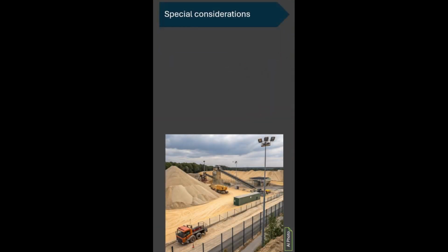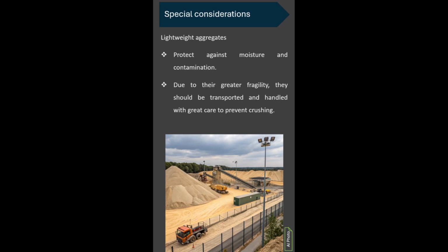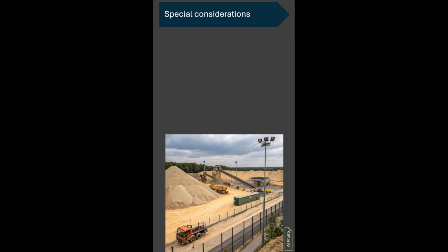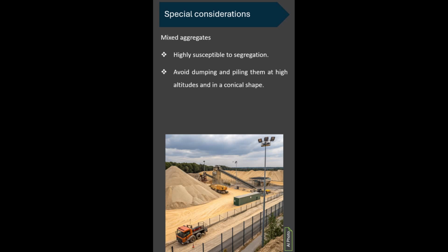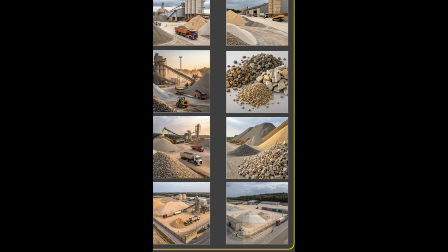Special considerations. Light aggregates protect against moisture and contamination. Due to their greater fragility, they should be transported and handled with great care to prevent crushing. Mixed aggregates, highly susceptible to segregation. Avoid dumping and piling them at high altitudes and in a conical shape.